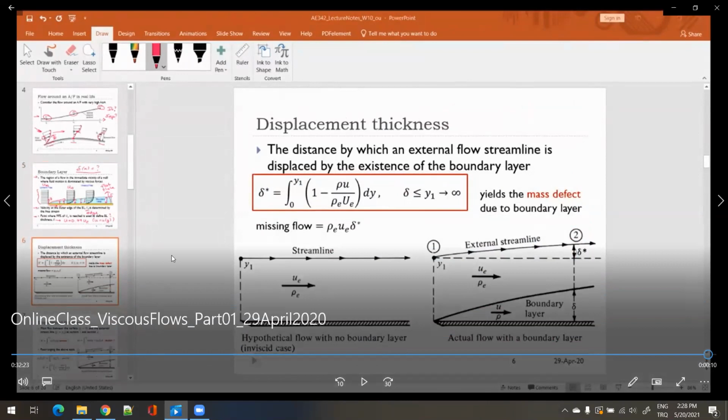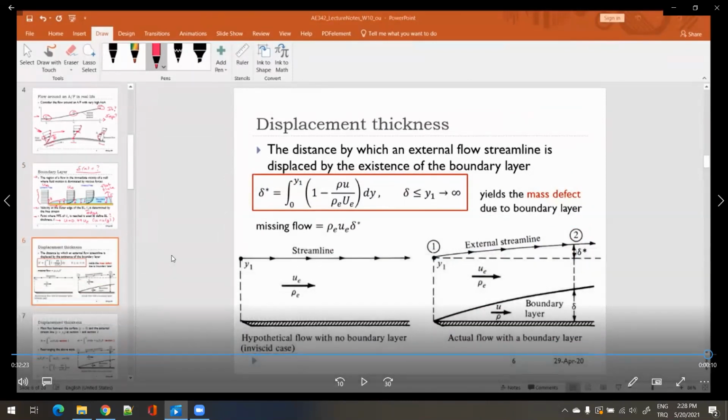Okay, so of course those comments were for the class times last year, but until this point in this video we have learned this conceptual definition of a boundary layer and the first important parameter of a boundary layer, which we call the boundary layer thickness, the delta value. As I've explained in this video, delta changes with x. So along the flat plate, for example, it changes with x. We would like to calculate how it changes. That's one of our objectives.